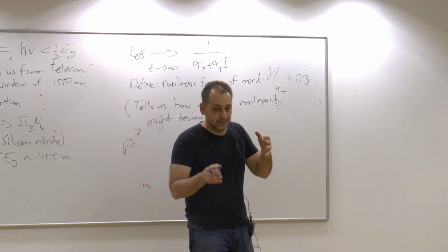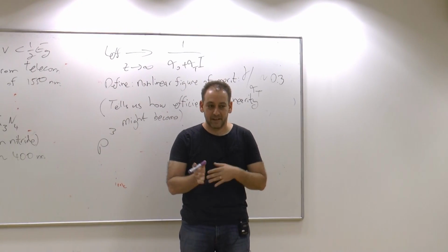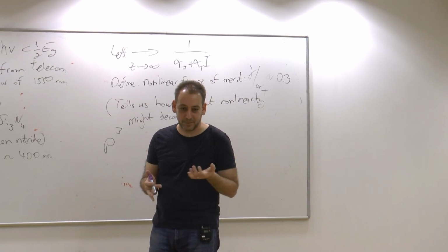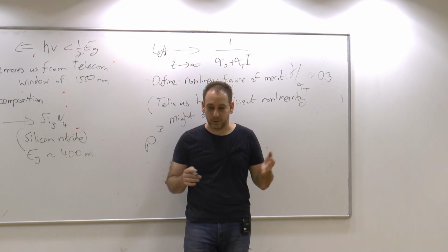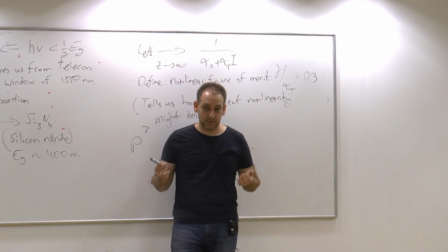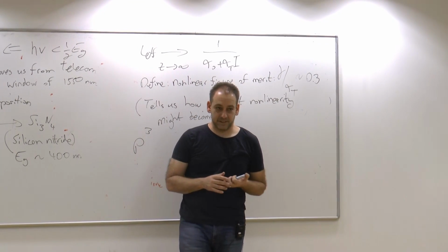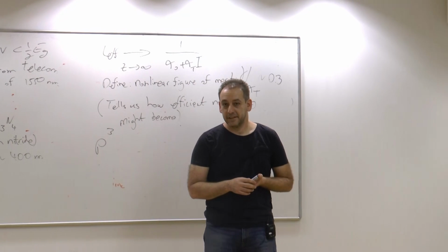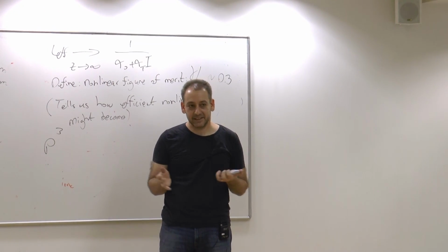So if your device and system is large enough and complicated enough, sooner or later you'll need to compensate for losses. This is done over fiber with erbium doped amplifiers, and we need an equivalent on a chip, so we need gain. And if this is not a good enough reason, then every system like this needs a light source, right?